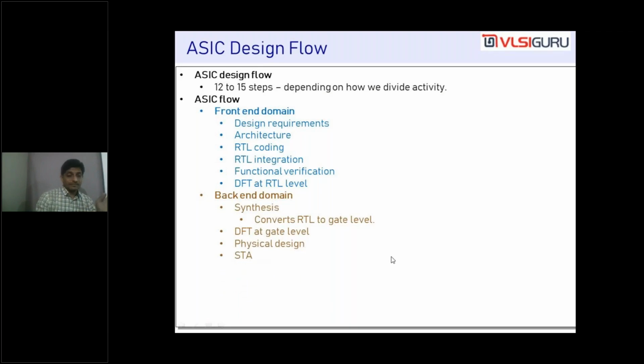STA. Next step is what? STA stands for static timing analysis. You will hear terms like setup time, hold time. To make sure that there are no setup time violations, there are no hold time violations in the chip. Anywhere in the chip, there should not be any timing violations. That role is called as STA.